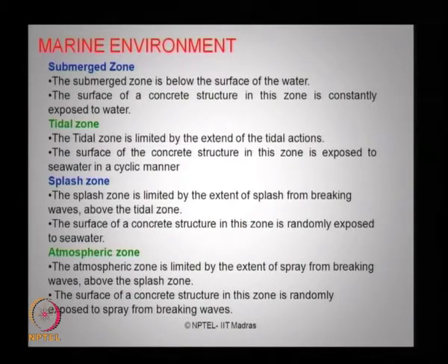The surface of the concrete structure in this zone is exposed to seawater in a very interesting, cyclic manner. So there is alternate wetting and drying in the zone, which is more dangerous for concrete performance in such an environment. The splash zone is limited by the extent of splash from breaking waves above the tidal zone.